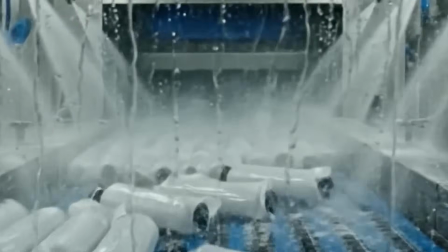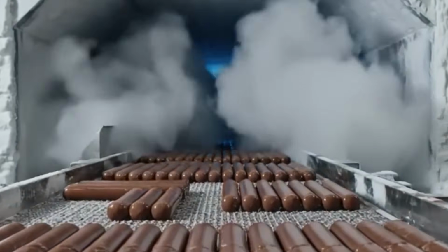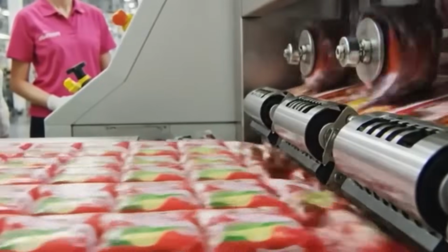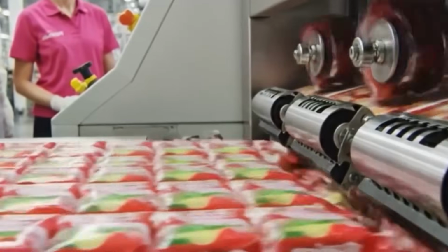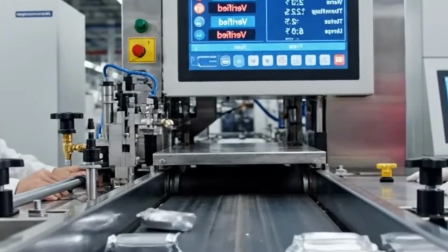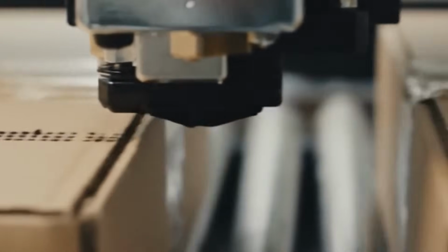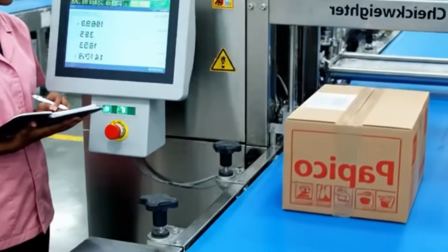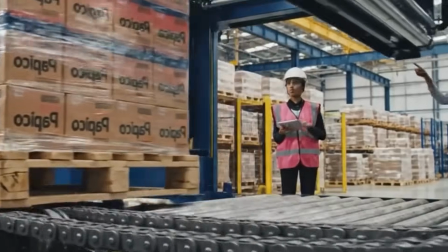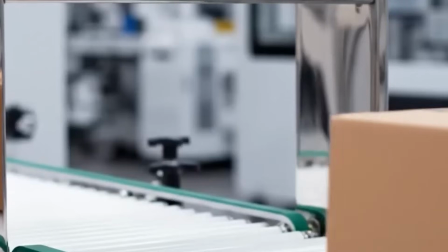Fillings, inclusions, and variegates are added at multiple points. For layered products, rotary depositors add jams, caramel, or chocolate syrup between ice cream layers. Inclusion feeders dose chocolate chips, cookie pieces, or nut fragments into the flowing stream before extrusion using volumetric or gravimetric feeders. Variegates are added using swirl nozzles or rotating spouts that inject sauces in spiral patterns into tubs.